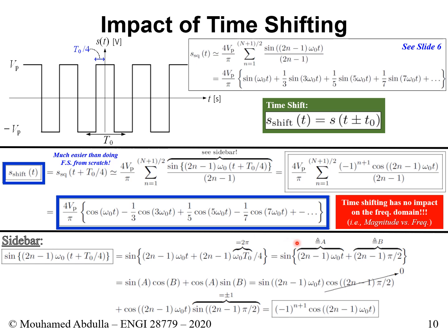But for us, we are practical people. We want to understand it the way that a spectrum analyzer does it. In a spectrum analyzer, phase has no role to play, and therefore we only look at it from a magnitude point of view. So from a magnitude point of view, any shifting you do on the time domain will not change your frequency domain. It has no impact.